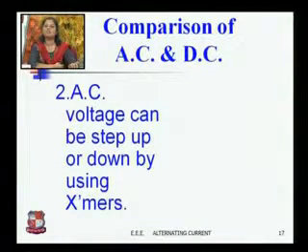As we know, our generated voltage is 11 kV, which is generated by a power plant. So the generator output is 11 kV, but we use AC supply for domestic purposes. And for domestic purposes, the value of the AC supply is 220 volt or 230 volt. So from 11 kV to 220 or 230, we can step down by a step down transformer. In the same way, you can change the voltage level higher than 11 kV using a step up transformer.